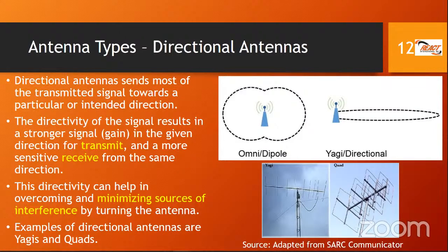But yes, you can have some antennas that are reasonably resonant over a range of frequencies or part of a band, but it hardly ever is going to be perfectly resonant on the entire band. That's why in the case of HF, you'll use antenna tuners and so on. Sometimes you can tolerate a higher SWR, but generally you're really aiming for resonance as well.